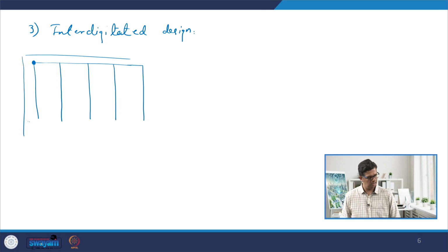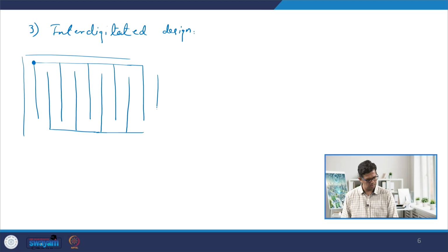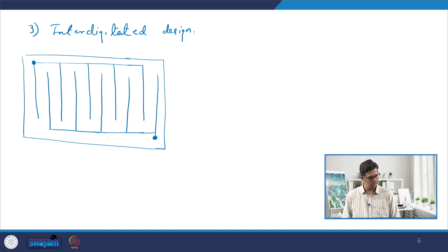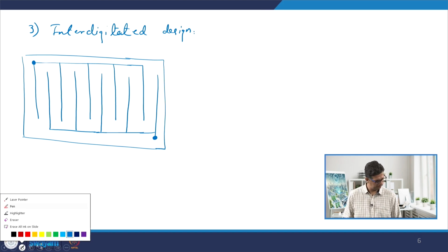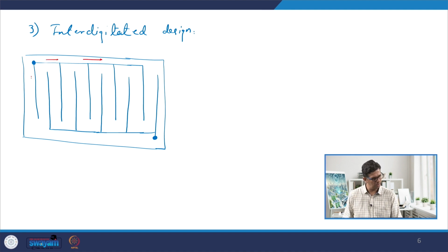The inlet channels are all connected. However, if you look at the exit channels, they are basically not connected to the inlet channels. So this is the entry. In case of hydrogen flow, it flows through like this, and while it flows through these channels, it basically travels through the diffusion layer to the exit channels.